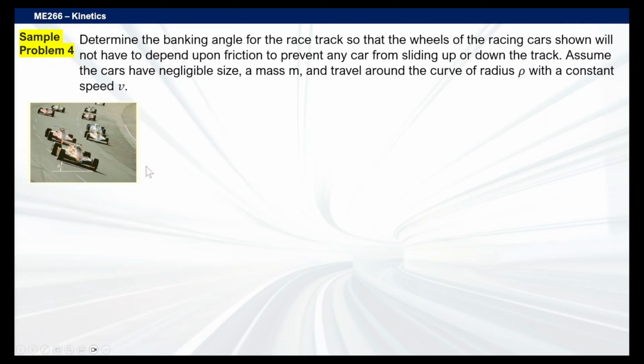If you're going to draw the free body diagram of this, it's going to look like this. We know there's going to be a weight. This is the tangential force, and this is the binormal direction. Let's just call it z for the meantime. We have the weight equal to mass times acceleration due to gravity and the perpendicular force. And here is a theta, and this is the banking angle essentially, and this is the normal. Essentially, this is the banking angle.